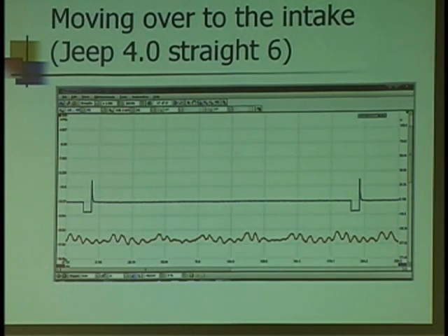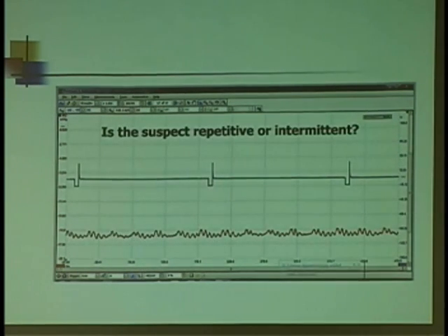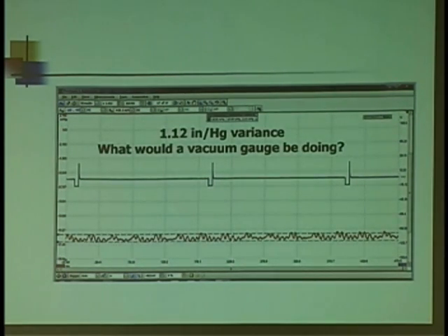How many guys are still using manifold vacuum gauge? Us old guys, we were brought up on those things. I still got mine, that really big fat gauge. You can still find them on the tool trucks. We actually use them for measuring carburetor fuel pressure, the old mechanical fuel pumps. Okay, and if you were looking at this as a manifold vacuum gauge, what would that needle be doing? Okay, and we've only got about an inch